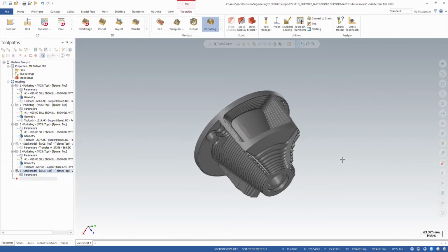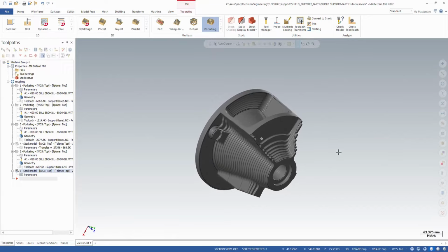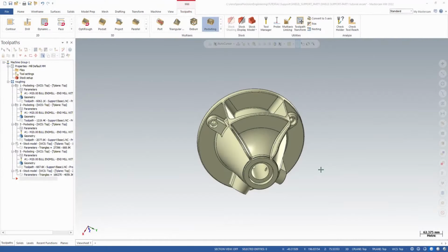So actually we are going to create like a false floor behind our part. And this is important. The floor that you're going to create, it has to be behind your machining features, okay? Because this is the deepest point of our roughing operation, the floor. Okay, so now let's quickly create that surface I need for my tool axis control.